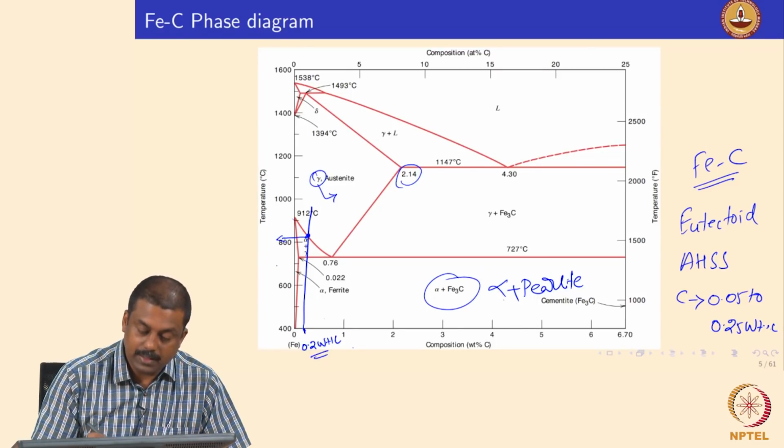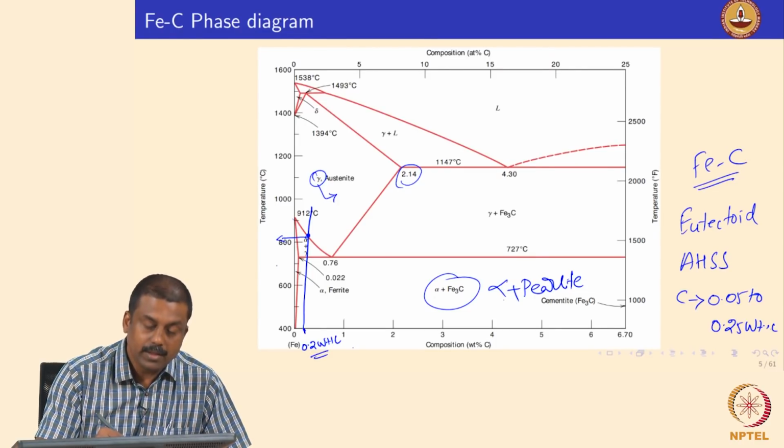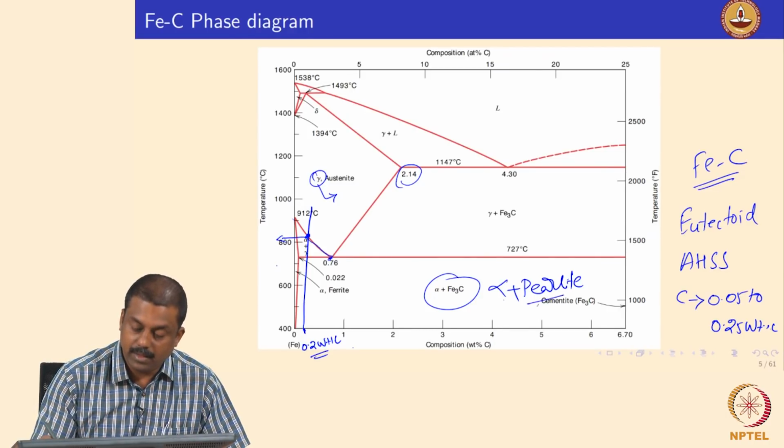So first you need to understand from this graph that if you have 0.2 weight% carbon and you are cooling down to room temperature, your austenite would keep enriching because of the formation of ferrite first. Then the moment the untransformed austenite reaches the eutectoid carbon concentration, you will end up forming pearlite.